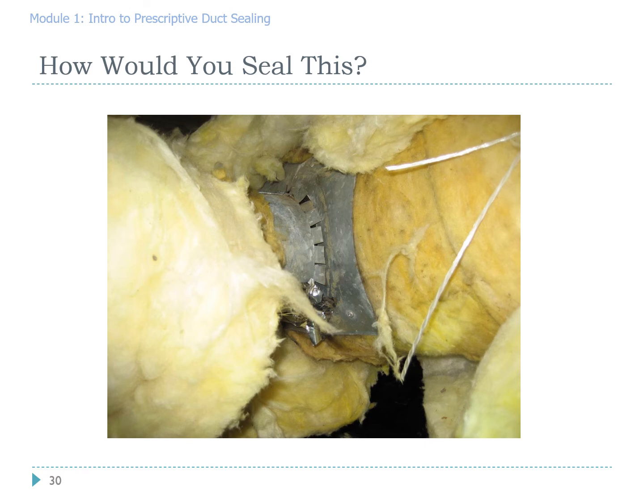Let's take a minute to figure out how we would seal this. As you can see, the insulation is actually underneath the sheet metal takeoff. We also have some notches right here, some fins, some tabs that were not exactly folded correctly. In order to seal this correctly, we would have to take the takeoff off and remove the insulation, because insulation is not an air barrier.